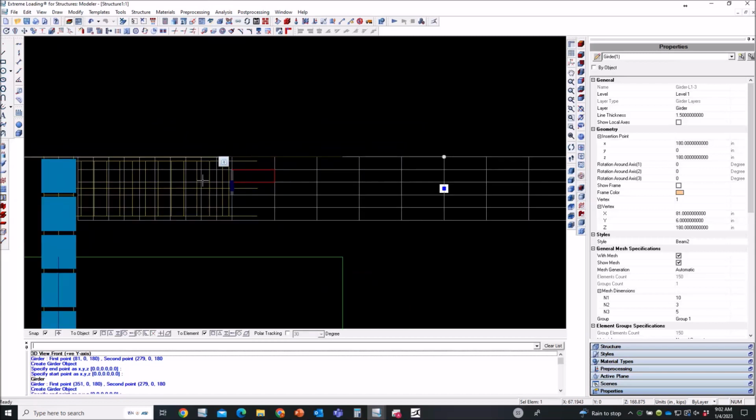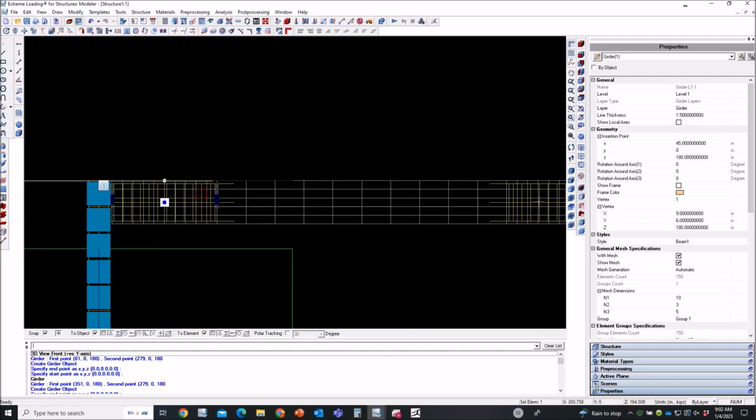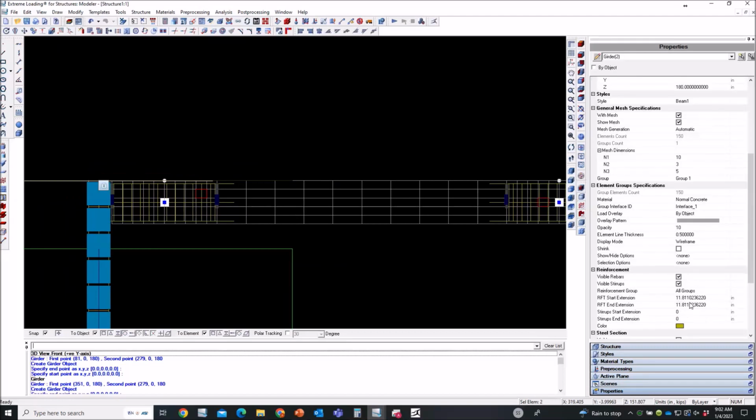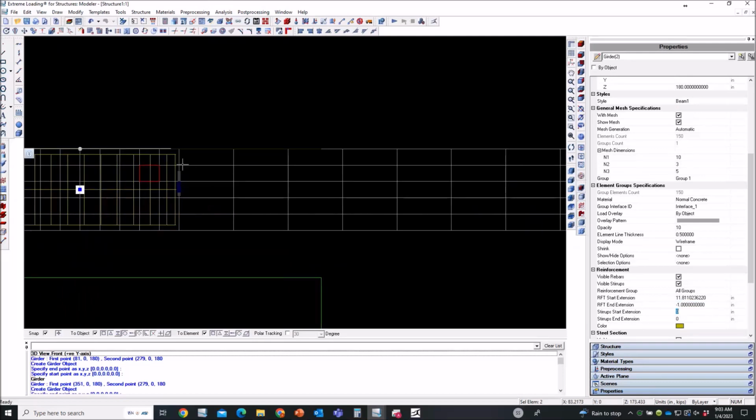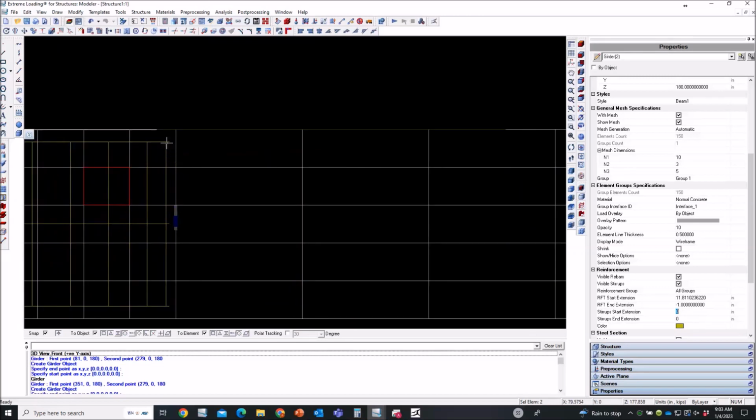The best way to do this is to select this beam, which is at the corner. Let's make it like both beams at the corner. And then I will come here at the reinforcement extension at the end of the beam and make it with a negative value. Let's put it -1 inch. This means that I have no reinforcement rebars that are going to be generated in here between this beam and this beam that's coming from the beam at the edge.